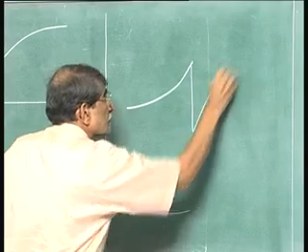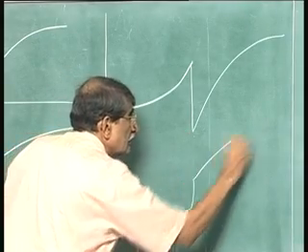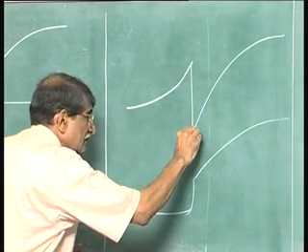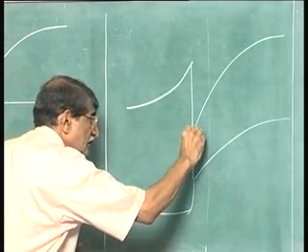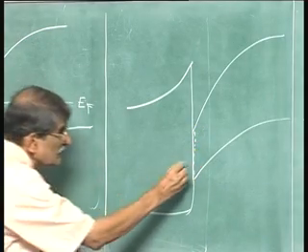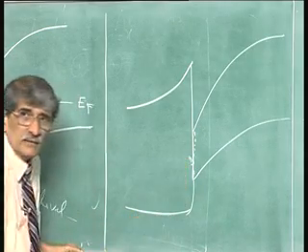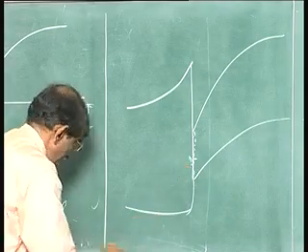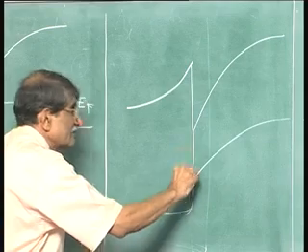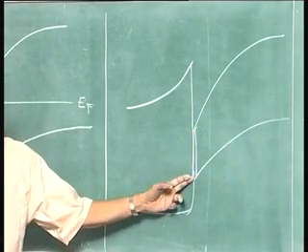What is the situation now? More number of electrons here on the gallium arsenide, less number of electrons here. But they have to just live together. So, what happens is charge sharing takes place, electrons from here to here move, okay, and this gets negative charge, this gets positive charge. A dipole layer is formed. In fact, the theory as formulated says that it is not a condition for minimum energy, it must be minimum. But even if you do not agree with that particular situation, ultimately charge transfer will take place and this will become equal as close as possible.